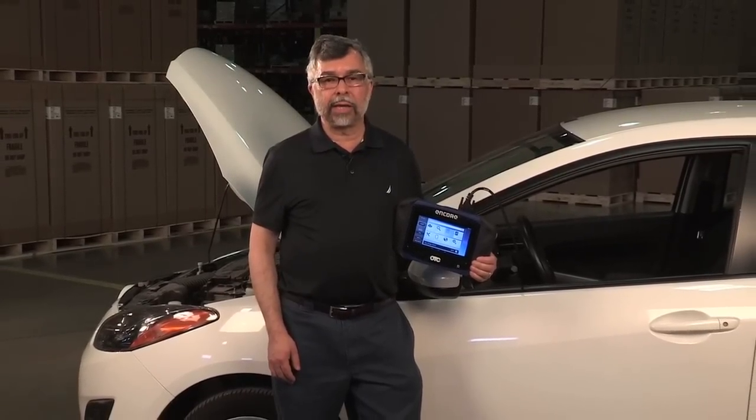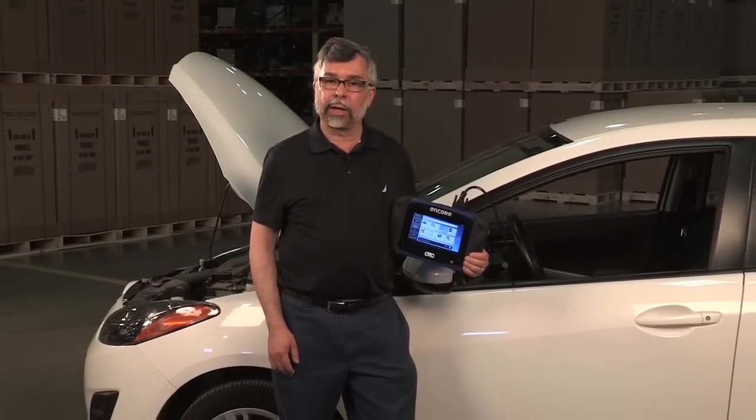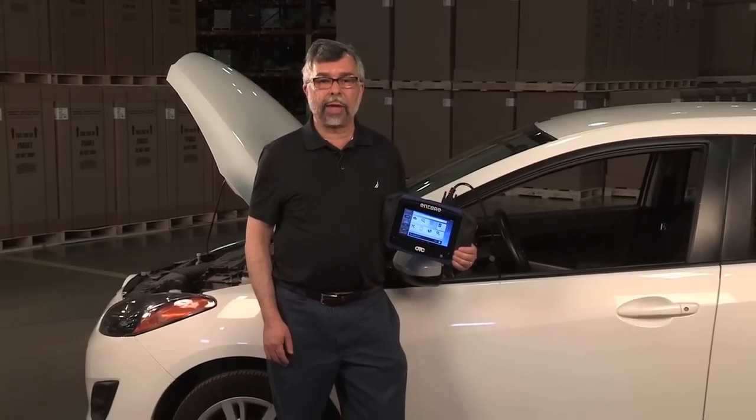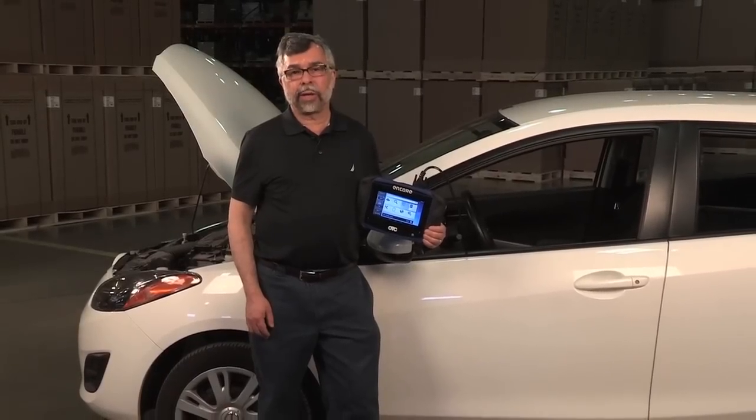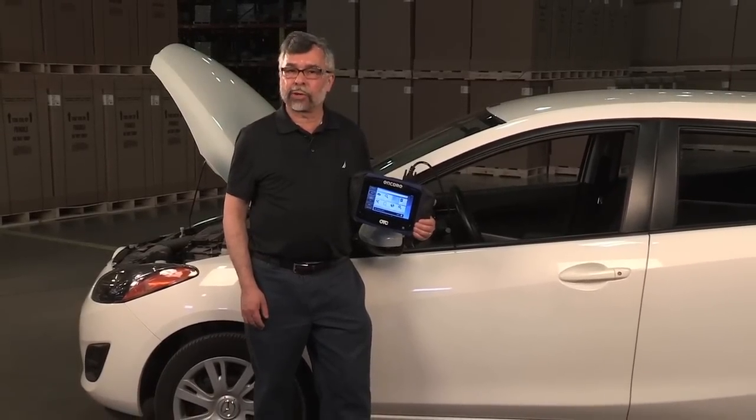Remember that VE is a calculation of the amount of air going in. With low compression, the engine will not be able to create a sufficient low pressure area behind the throttle plate for the atmospheric high pressure to overcome.